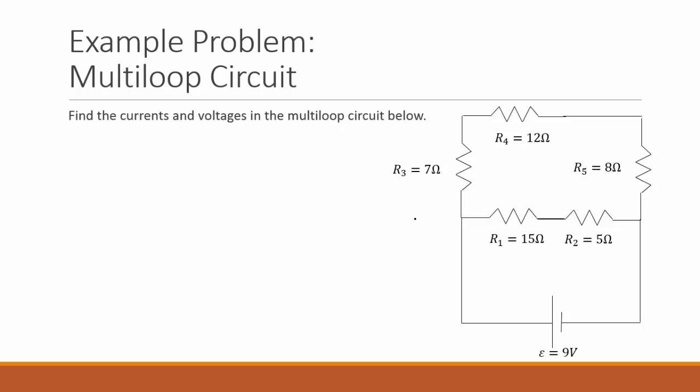Now, currents always begin and end on junctions. And here are the two junctions. So in any stretch between those two, it has the same current. I'll label the bottom current. I'm going to guess that it goes this way, again using the fact that it tends to cross through batteries in this direction, which I tend to phrase as from the negative to the positive, which means inside of the battery.